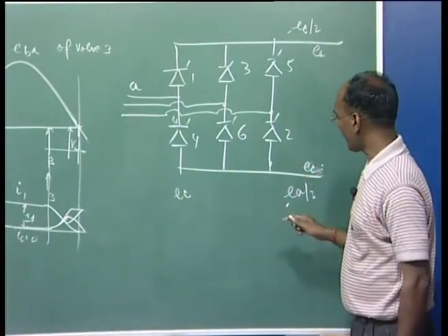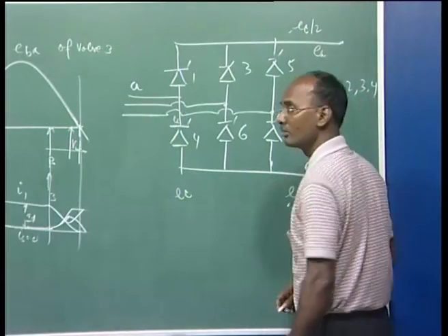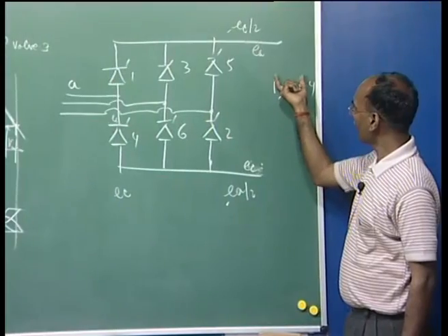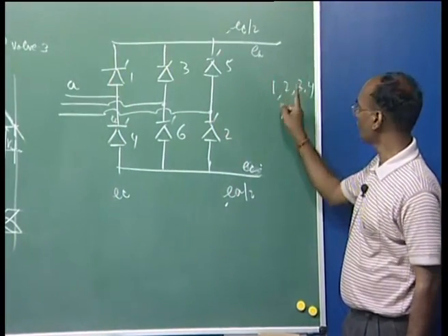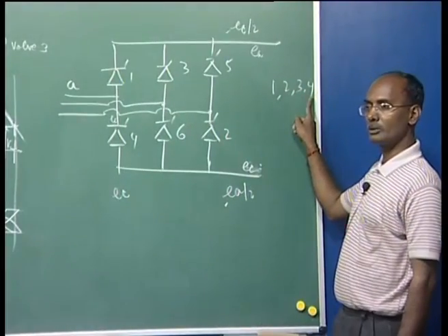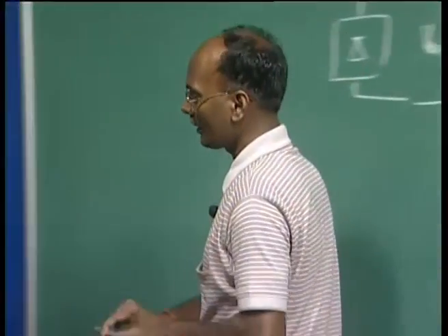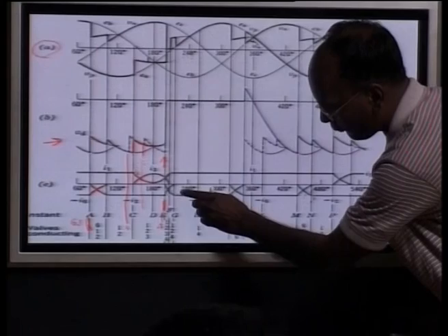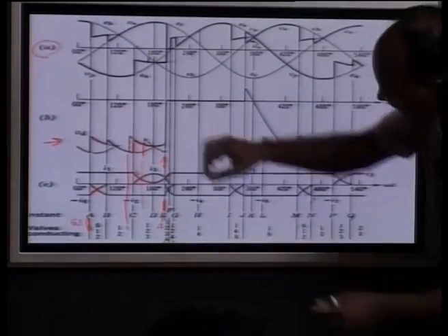There is one condition, as I said, where there is conduction of 1, 2, 3 and 4 here, and for 1 and 3 here the commutation failure occurs, even though the 2, 4 commutation is going to take place. You can see in this figure that the commutation between 2 and 4 is this period U, but for 1 and 3 this period is before that.